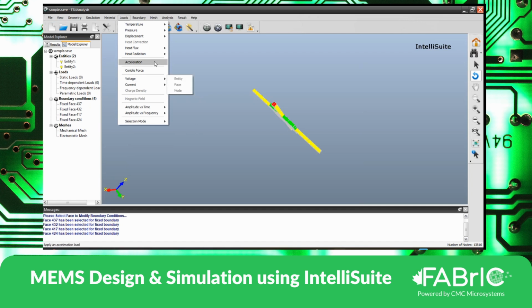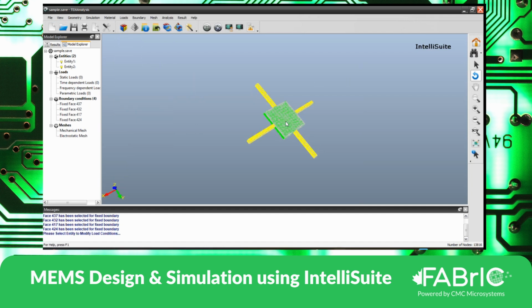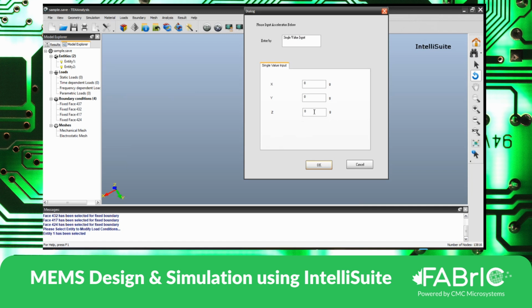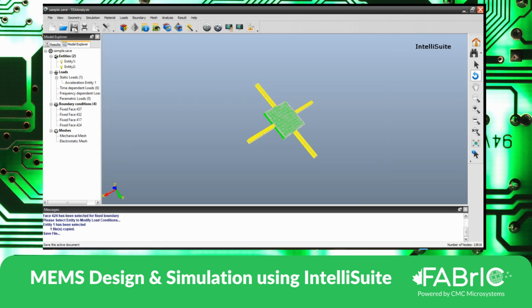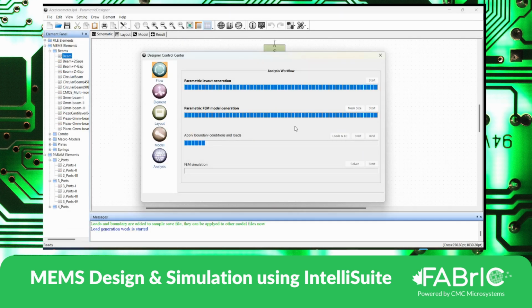And the load, since this is an accelerometer, I would apply, say, 5G. I save this. Oh, sorry. I think I'm trying to do a natural frequency analysis. For that, we don't apply any load. Okay, so I just saved the file and click OK and then click Start.